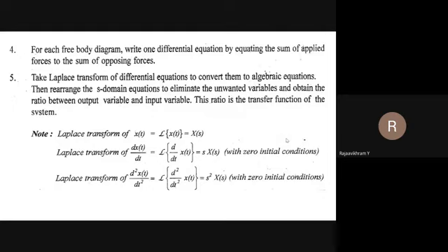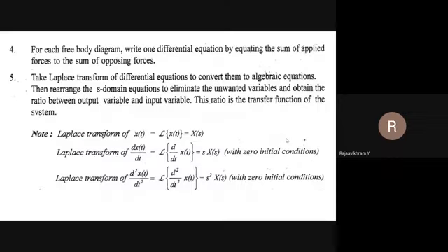What's my transfer function? Transfer function means output of the system divided by input of the system. Note the Laplace transform of x of t: the time domain is converted into the s domain. Laplace transform of x of t is capital X of s. The Laplace transform of the first order derivative dx by dt is represented by s into X of s. Note that these are all under the assumption of zero initial conditions.